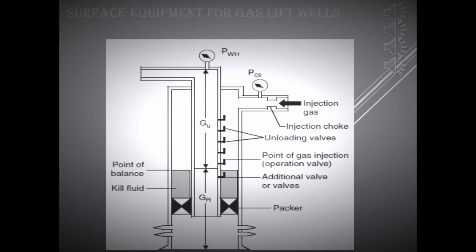40 minutes, 1 hour, so on, when it will be closed and there will be no injection of gas in the well. The other is the injection time, say 1 minute, 1 minute 30 seconds, 2 minutes, 2 minutes 15 seconds, 2 minutes 30 seconds and so on. With the shortest possible injection time, the required volume of gas should flow into the casing.